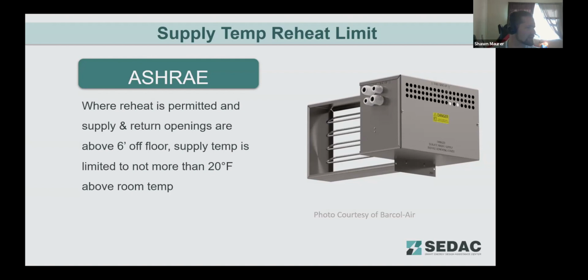We had a question come in for the occupied standby. Are there provisions that allow the zone to turn on when humidity rises above set point? Since there are humidity control set points in ASHRAE and others, I expect that that is the case. And I believe that would be contained in the actual humidity control sections of ASHRAE, since the actual occupancy sensor section only references temperature. I would look at the humidity control sections in the code and see if there is something there that overrides that particular occupied standby setting.